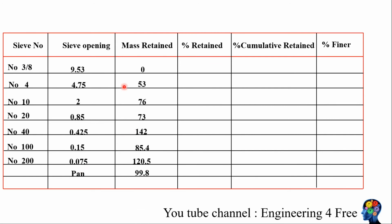To calculate the percentage retained, we have to know the total mass. You add the mass retained on each sieve and you will get the total mass. The total mass is 649.7 grams. Remember that you will use this figure while calculating percentage retained and not use the 650 gram.